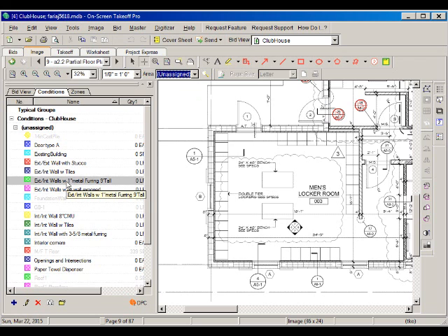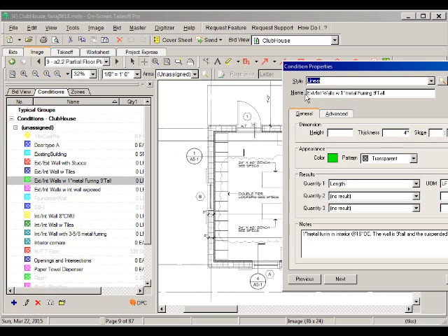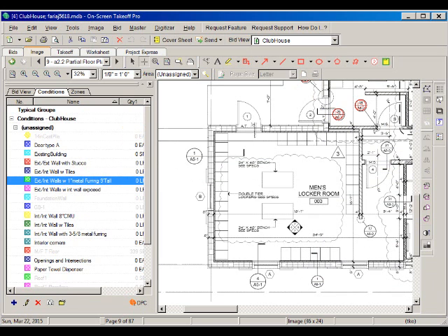So we're going to estimate the interior walls with 1-inch metal furring, 9 feet tall. The height of the wall is then 9 feet. The thickness, we can set it to 1 if we want, or we can leave it at 4. This is really going to be 1. Although sometimes people tend to use a thicker value because we have the 1-inch furring, and then we have also the 5/8 for the drywall.